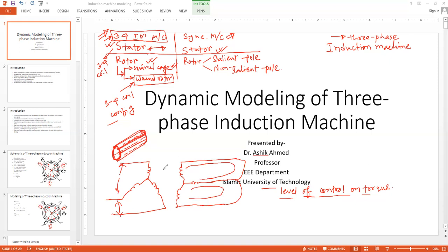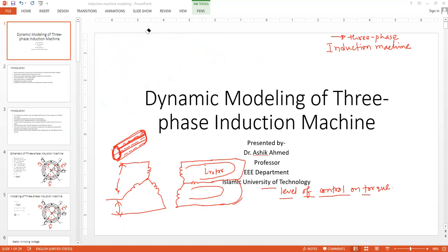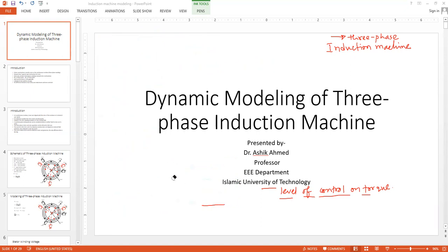So if you're not shorting this out, then the path is not closed, and ultimately you don't get any current. I rotor becomes 0 in that case, and you don't get any torque out of the wound rotor machine. Okay, so these are the very basic things. I just gave a small review on that, just to have you recap on the constructional differences between the synchronous machine and the wound rotor machine, three-phase types, both cases.